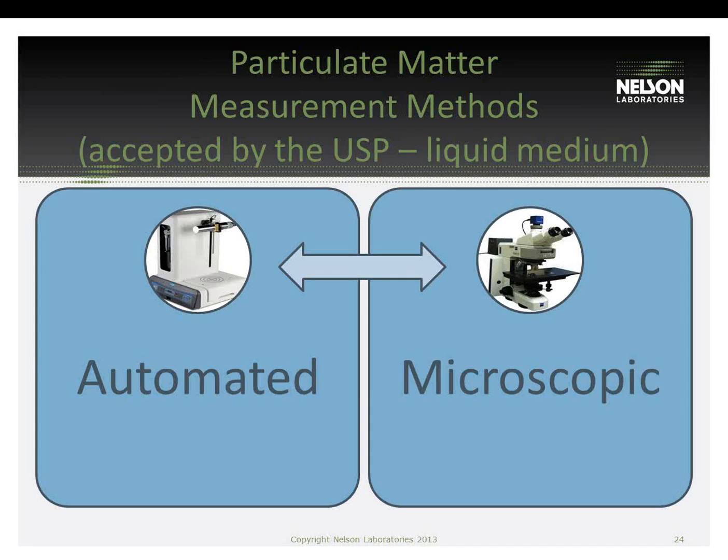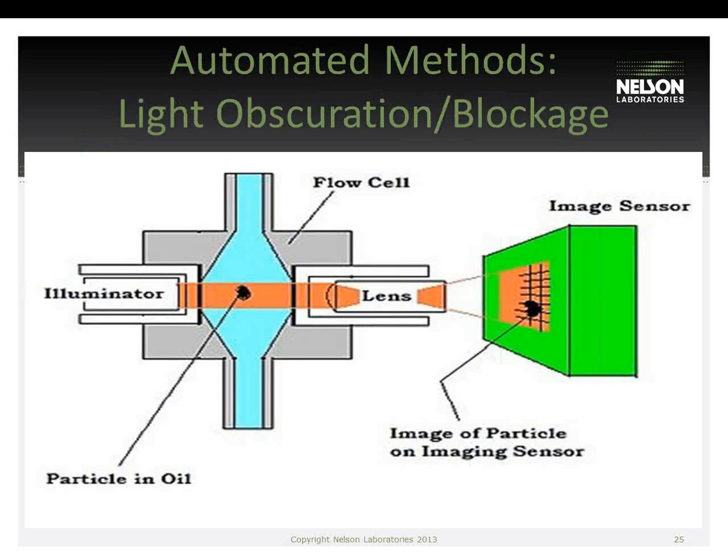Getting into measurement methods, modern particulate testing includes two main methods: an automated method using a piece of equipment that's usually calibrated and doesn't contain any kind of human bias, and then a microscopic method, which is a manual method whereby particles are manually counted and sized, and data provided that way. Both of these methods are equally important, and we'll get into those a little bit more right now.